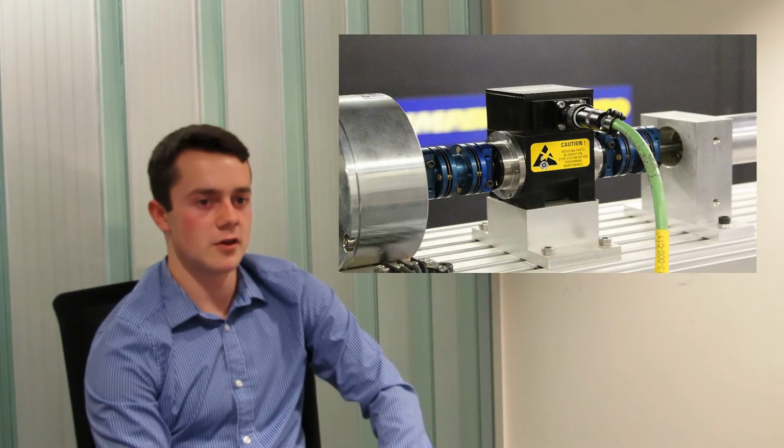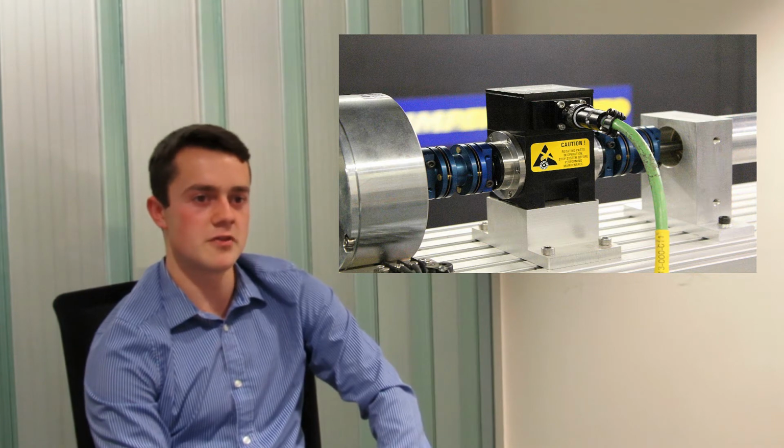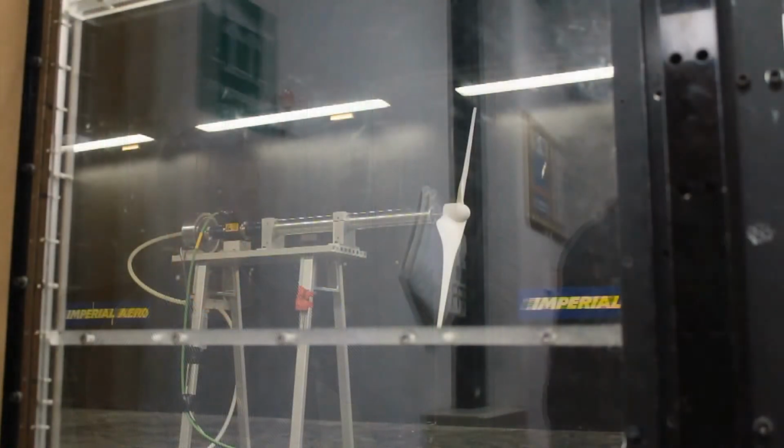Once the manufacture was complete, the turbine was tested at various wind speeds in the Honda wind tunnel. Before the test began, the wind turbine was allowed to spin freely until it had registered its maximum RPM. An electromagnetic brake, called a hysteresis brake, applied a controlled mechanical resistance to slow the turbine to its minimum operating RPM. The wind tunnel controller was then preset with these values of maximum and minimum RPM.